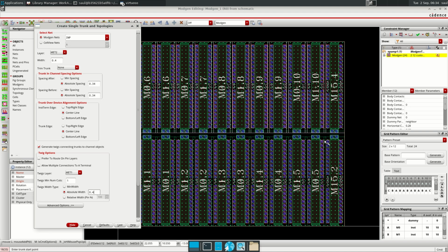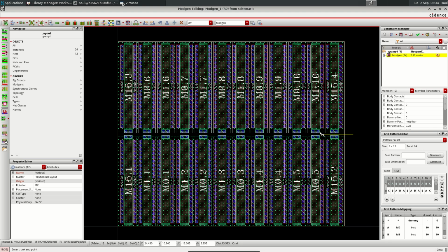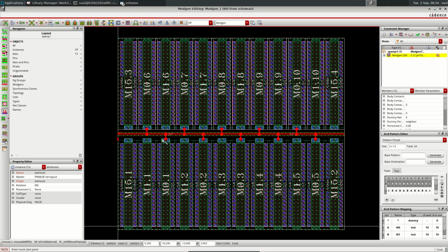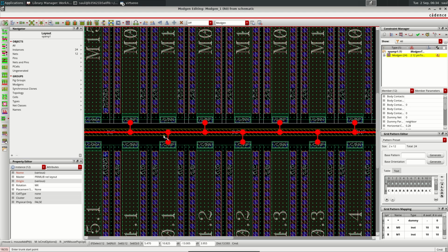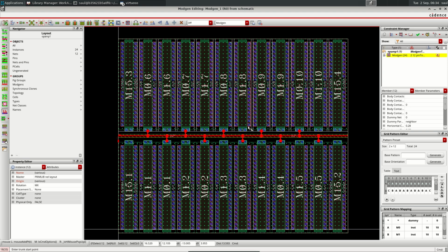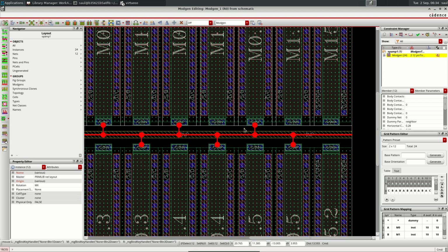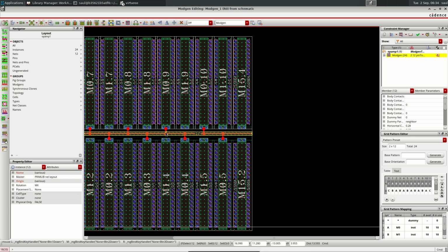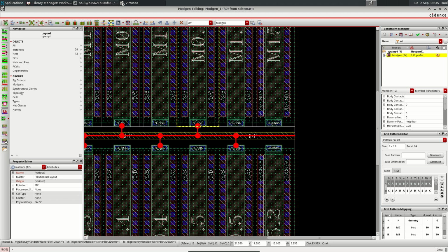So what I can do here is just pass one left click, and then we just passed a line, second click, and it will create this connection here. So I press ESC, and we see that a metal 2 track has already been created, and the tool has detected what are the nodes that need to be connected. So each of these is called a twig.